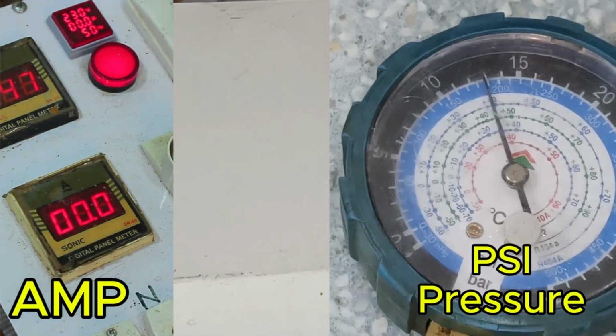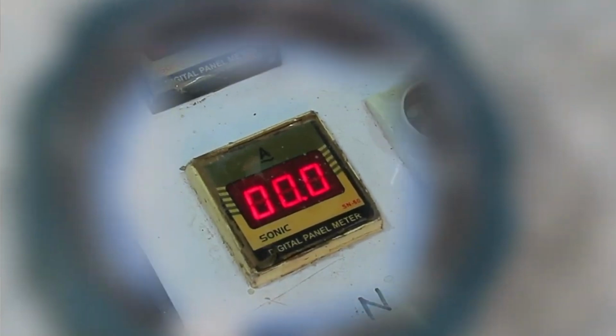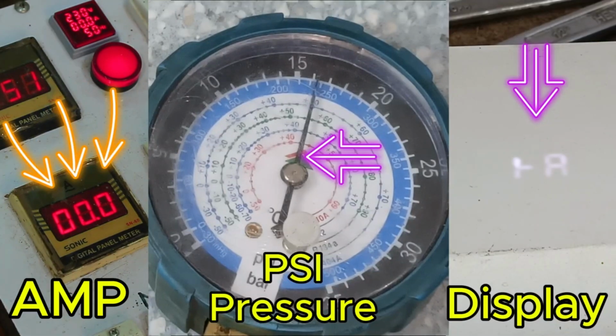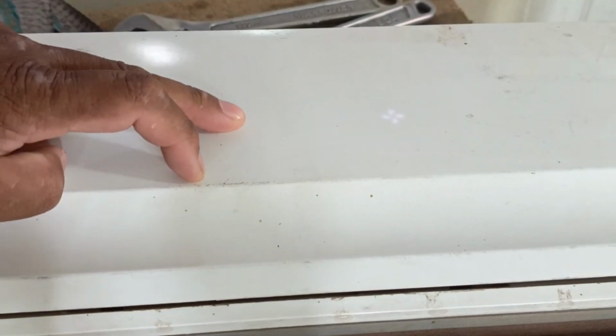And now its compressor has shut off. I think it only worked for about 4 to 5 minutes. The amperes have dropped to 0, and the pressure gauge needle has also started rising. The display now shows an IR error, which is very strange. There is not actually an IR fault in this unit. Currently, it is showing 16 degrees on the display.